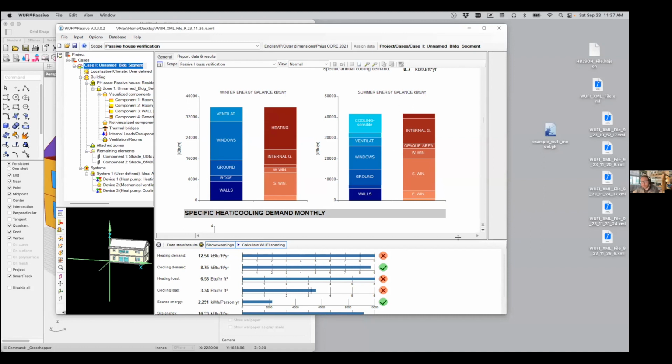So we've done a really good job of beating back the heat loss through almost everything. And we're at 12.5 kBtu per square foot for heating demand. We're supposed to be at 8. So can we get all the way there by improving the window performance, right? That's the question that we want to pose next: what can we do to improve the window performance?